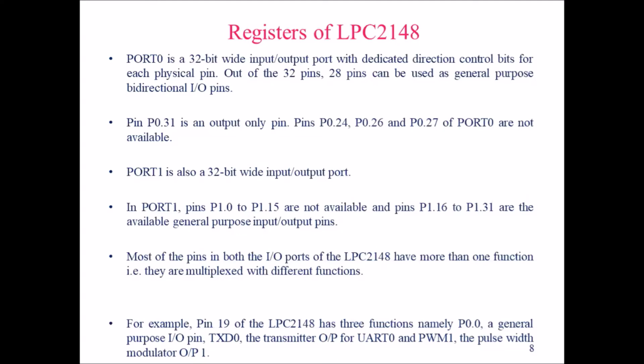Port 1 is also a 32-bit wide input or output port. In port 1, the pins are named from P1.0 to P1.31. Here P stands for the port, 1 stands for the port number, and the number after the dot is the pin number, so 15 stands for the 15th pin.